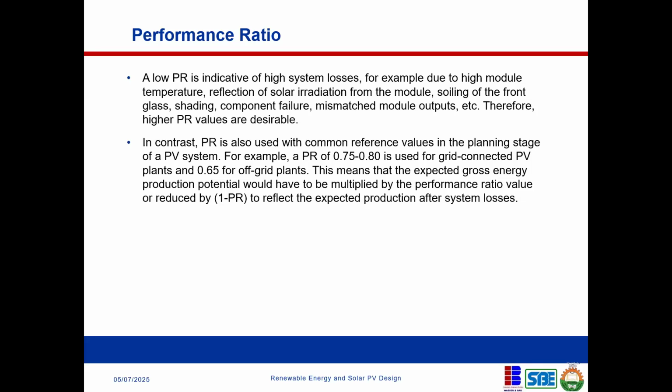If you're doing an off-grid system, it is recommended that you use 65%. Now, these are assumptions at your design level, right? You can decide to use 70 if you choose, or you can decide to use 75 if you want to, but I would want to keep it at best 75. I would not encourage you to go above, so that you don't overestimate. That's the reason why I recommend 75 at maximum.